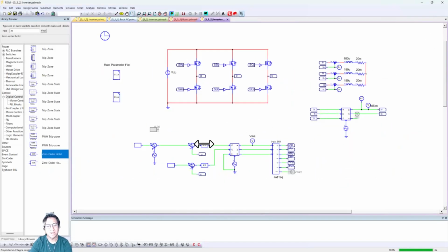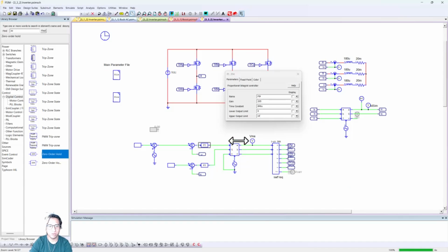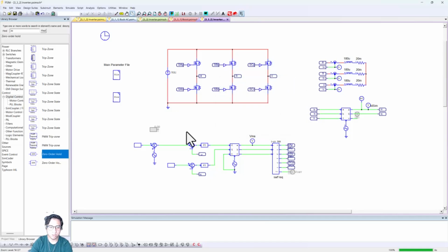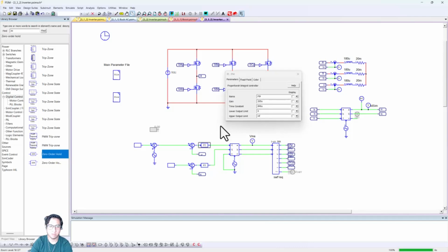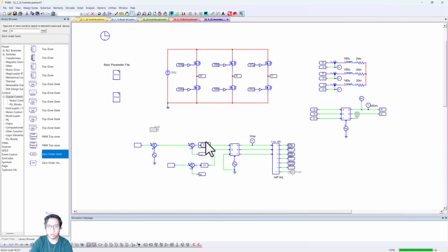So if we look at the PI controllers, both, on the gain, I forgot to place this micro suffix or prefix, and this actually fixes it. So play around. If something happens to your modulation waveforms, pay attention to your controllers, right? It's very likely your controller is not doing its work. On another occasion, a user had their PI controller parameterized, so they had variables here, and one of the controllers had them, but the other one didn't.